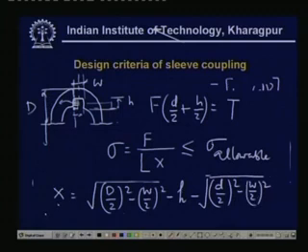So this is how we calculate x. That is plain and simple if you consider two right angle triangles here, and then this equation comes automatically. After having calculated this value, you can check for the stress sigma, and that must be less than this allowable stress. So this is how we have to check.